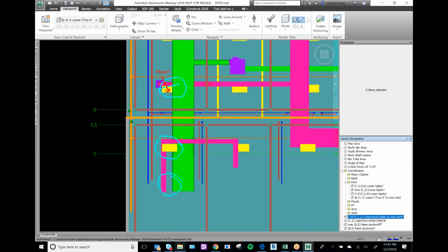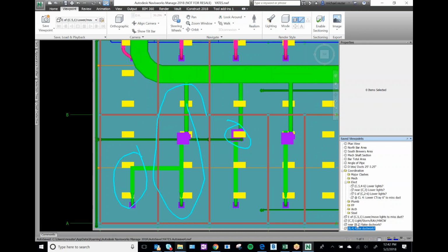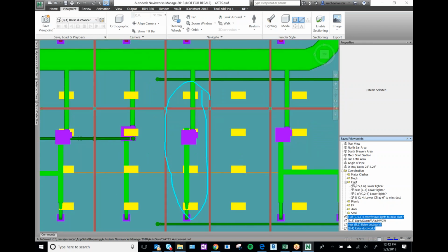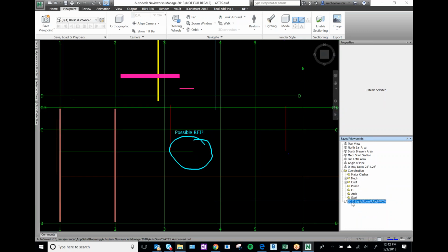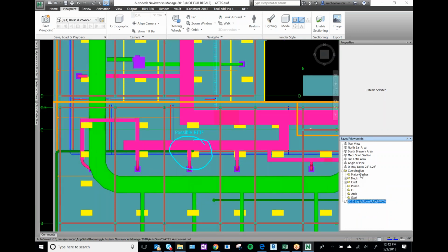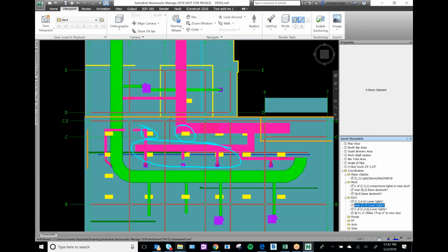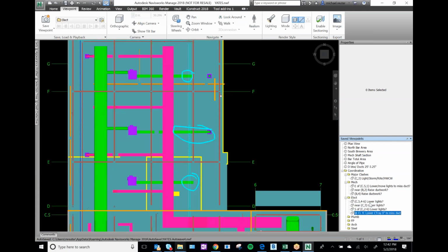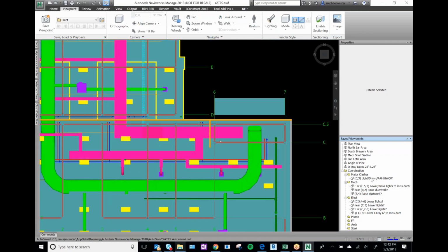Now this one is a ductwork one. This is a ductwork, this is a ductwork one. Drag and drop those in. Now I've got my major clash. So you see what I did? Now I've also assigned everybody their clashes. This is their work list. This is our discussion list during the meeting. So that's basically what I did.